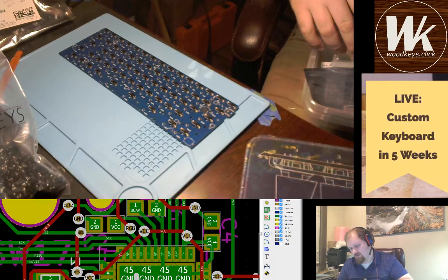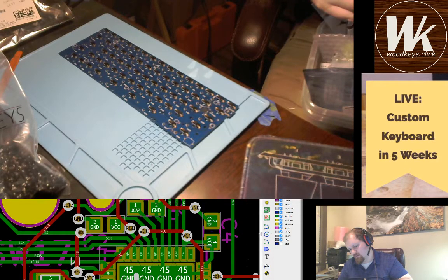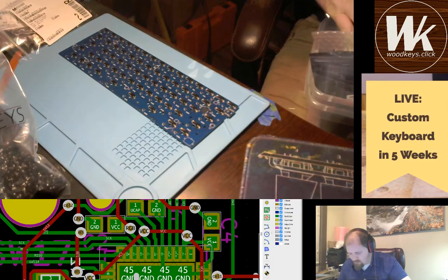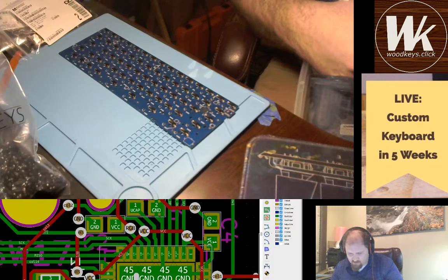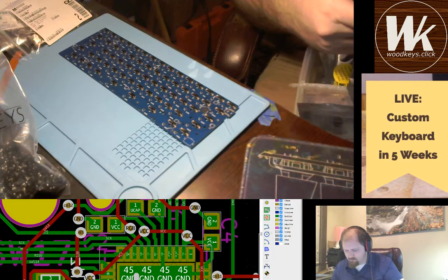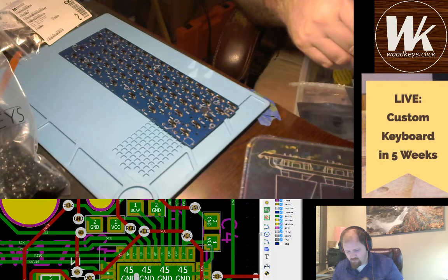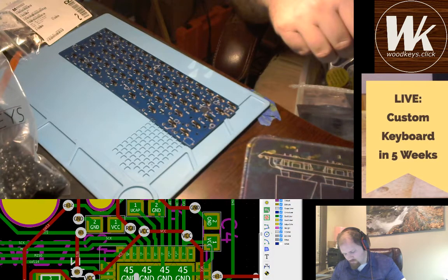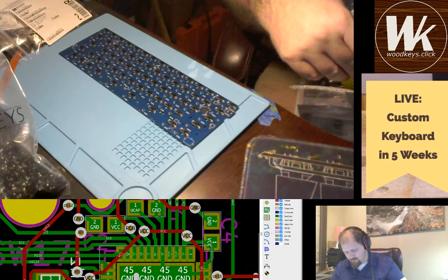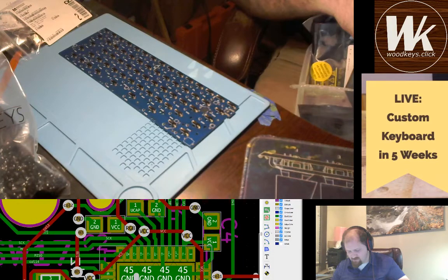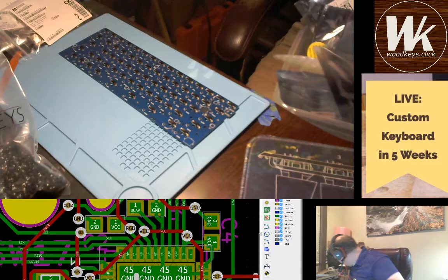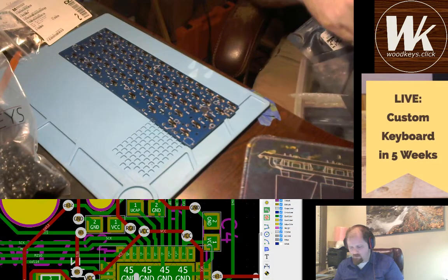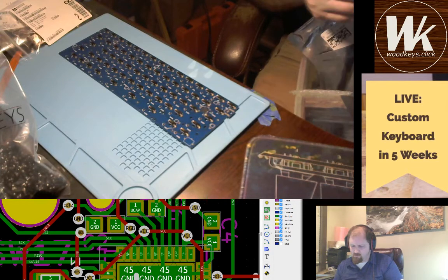All right, we've got a micro USB, mini USB port. Normally I would put USB-C on a new board, but since I'm assembling them by hand, I didn't really want to do that. I do have a new USB-C that is easy to assemble by hand because it only has one row of pins, but I hadn't used it yet. I just got them in along with this shipment of PCBs, so I wanted to make sure that I had something that was going to work for this.